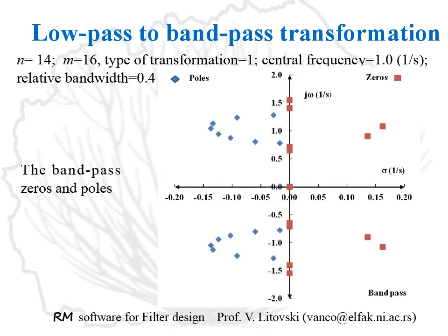And here is the pattern of the new poles and zeros, symmetrically around 1 and minus 1, or around omega c and minus omega c, practically repeating the low-pass prototype. We have it up and down, and as one can see, a new transmission zero is created in the origin as a counterpart of the zero which is at infinity.